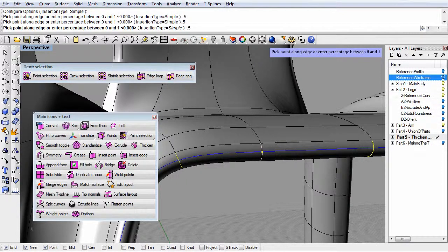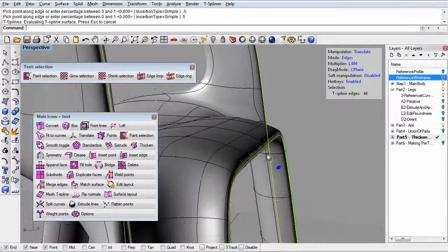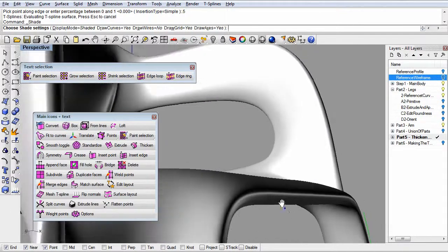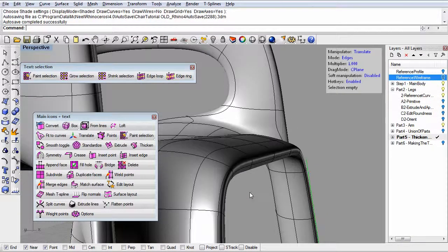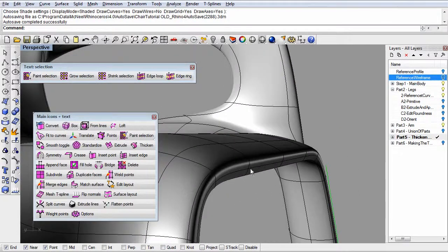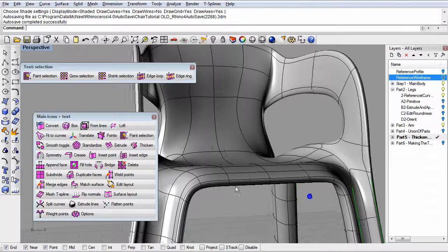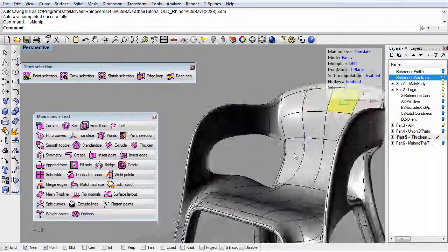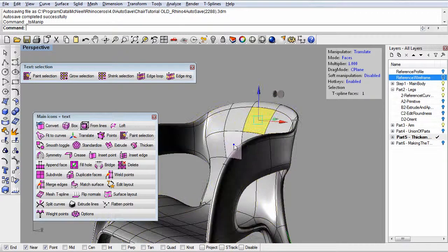Then by adding this extra ring or this extra edge loop into my model, it will really tighten that up. So you can see if we change the shading a little bit, that gives something that's, I mean, really almost kind of like a radius to that, that's a little bit tighter than what we started out with. So you can continue to add additional edges to your model to get that tightened up however you'd like it. And the important thing to remember is this is always a T-spline, so we can still go through and edit it and make updates.